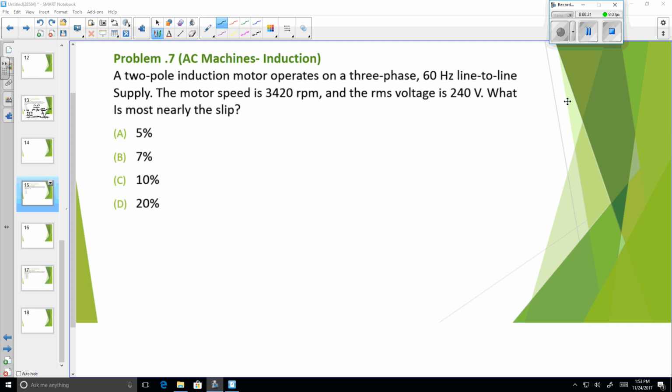Now, if we need to discuss the concept of operation of an induction motor, you need to apply input electrical power. So you apply three-phase voltage on the stator winding, and that will produce a rotating magnetic field in the stator winding that rotates at the synchronous speed. That synchronous speed depends on the frequency of the applied voltage in the stator winding. So the synchronous speed N is equal to 120 times the frequency of the applied voltage divided by the number of magnetic poles.